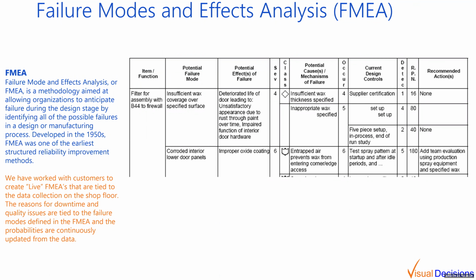And it's typically disconnected from the way that people gather information on the shop floor. In fact, I've yet to visit a single company that uses the failure modes that they've defined within their FMEA as the reason codes in their data collection system or their tick sheets or whatever out on the shop floor. And that disconnect just doesn't have to exist.